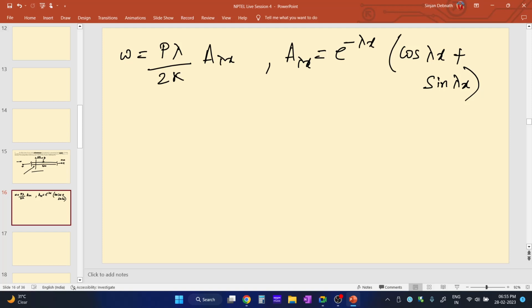In the last two questions, we were trying to find out the bending moment and the deflection at the point of application of load. So in those questions, the value of x was 0, because we were finding the deflection and bending moment at the load application point itself. In this question, we are trying to find the deflection at a point 1.5 meter towards the left side of the point of application of load. So here x is equal to 1.5.